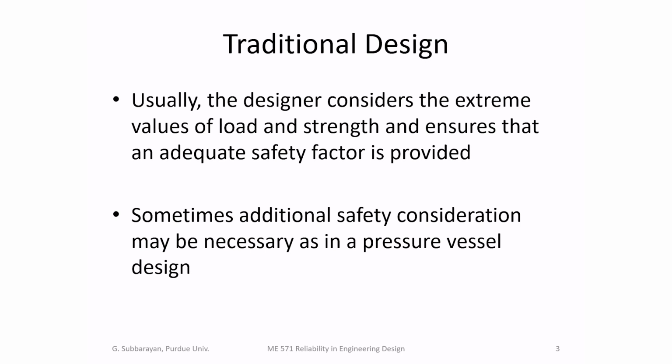So we basically use a safety factor to ensure that the load, the stress, for instance, will not exceed some allowable stress, which is strength, nominal strength. Okay, nominal, because it may not be the real. So nominal strength divided by some safety factor. So the allowable stress is nominal strength divided by a safety factor, and we ensure that the stress is always lower than the allowable stress.